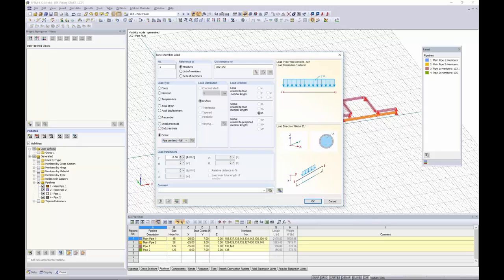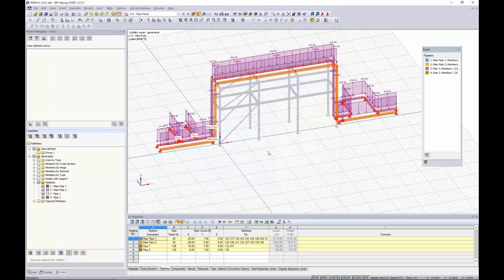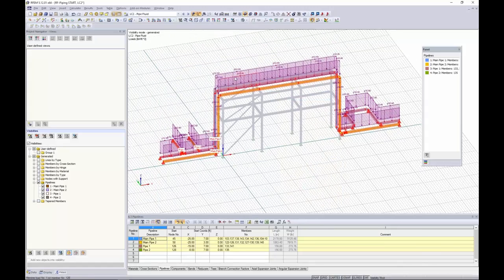For today, we'll assume it's completely full. We'll assume that maybe water is being applied through these particular pipes, so a specific weight of -62.4 pounds per cubic foot, and I click OK. So now visually I can see this load being applied to all of my members here.